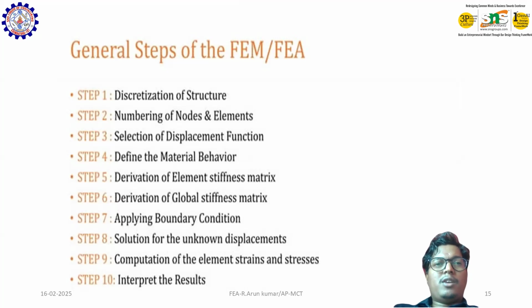For example, say it is a cantilever beam, which means one end is fixed. So I consider node one is fixed. So what about the displacement? Here there is no displacement. Whenever a node point has zero displacement, you have to eliminate the corresponding row and column. I consider u1 is 0, so you have to eliminate the row and column for node one, the first row and first column.